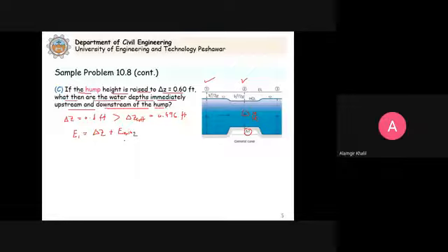So now in this case, we want to calculate what? Because the hump is greater than the critical hump height, there will be damming action. Clear? There will be damming action. So it means that the depth will no longer be 2 feet here. The normal depth which is given in the problem is 2 feet. But now that the hump height is greater than the critical hump height, as a result there will be a damming action. So the water surface will be like this and it will reduce to the critical.